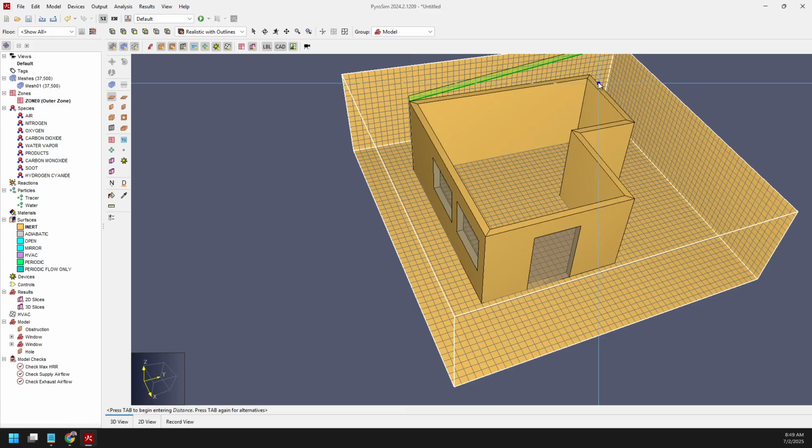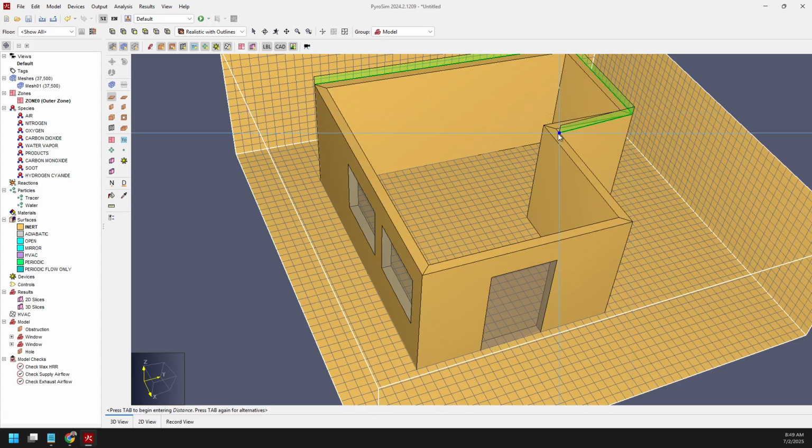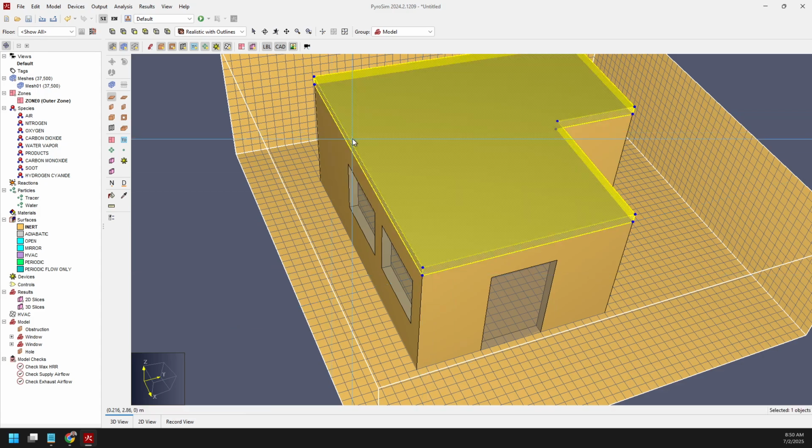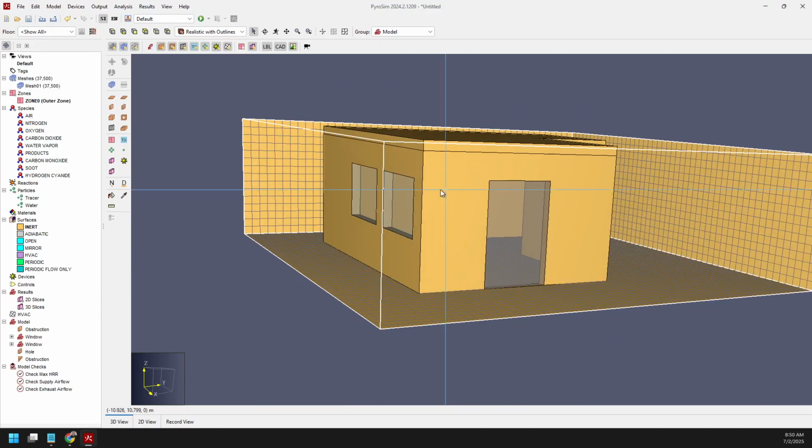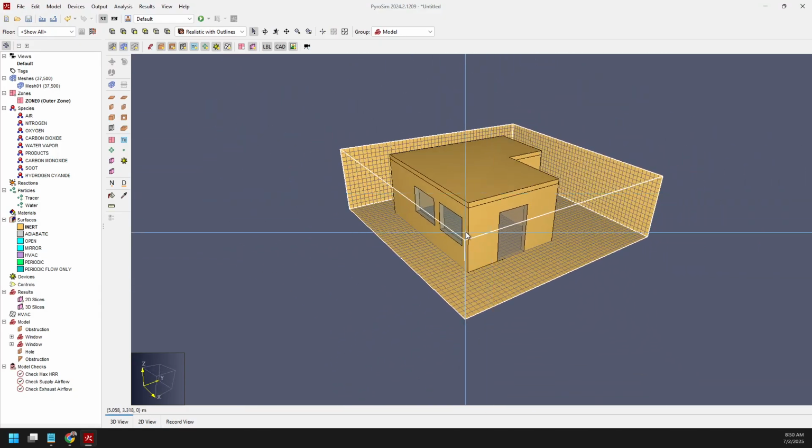And then we'll put a little roof on it by using the slab tool. And I'll just click around the perimeter. Oh, I did an undo there. There we go. Click. And then we'll finish, close it. And now we have a little floor or ceiling slab on there.